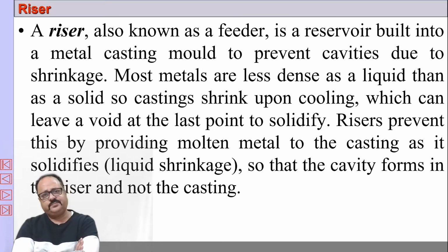When the liquid metal starts to freeze, its density increases, therefore it will shrink. When it shrinks, there should be enough metal in the riser to compensate for that shrinkage. So a riser is an extra void, a reservoir, a feeder, created in the mold to compensate for liquid shrinkage of the molten metal inside the mold.